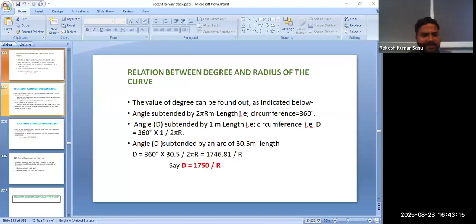These are the assemblies of ACD, anti-creep devices, used on the switch and tongue rail, and we measure its behavior using creep posts. Here it is, creep post as ATS, and in between the crossing body to measure its creep, meaning its behavior of movement. These are the proforma of our measurement.